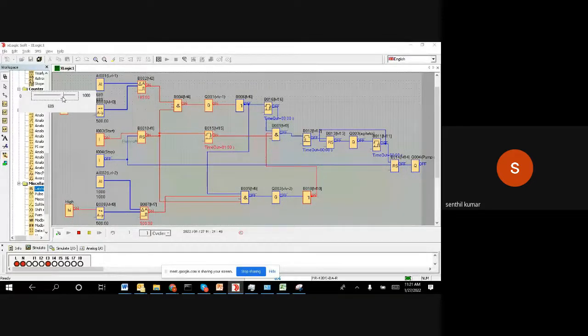So once it comes less than 500, I can punch a value directly, 501. So now we have 501, like 499 liters passed. Still the valve is open because one more liter is there. But still you could see the second valve is closed, the agitator is stopped, the pump outlet is stopped. Okay, now I'm going to simulate 499, which is 5 liters passed. So 500 liters passed actually.